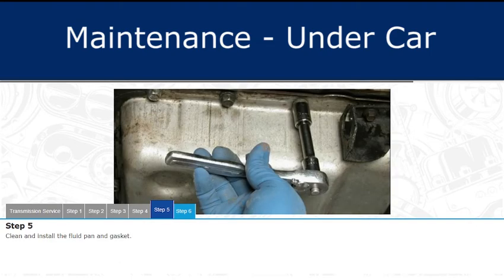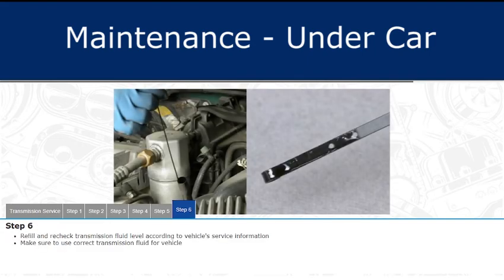Clean and install the fluid pan and gasket. Refill and recheck the transmission fluid level according to the service information for the vehicle being serviced. Make sure to use the correct transmission fluid for the vehicle.